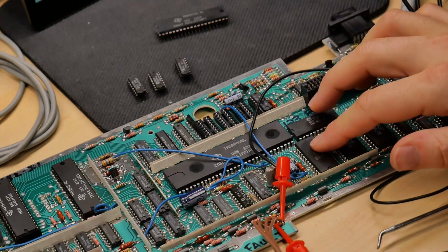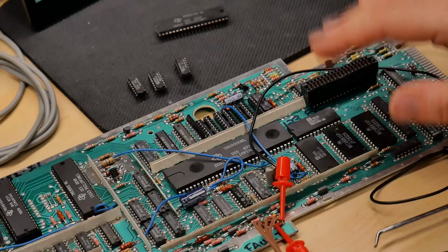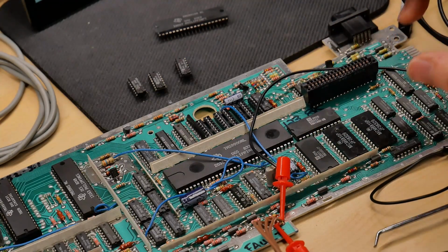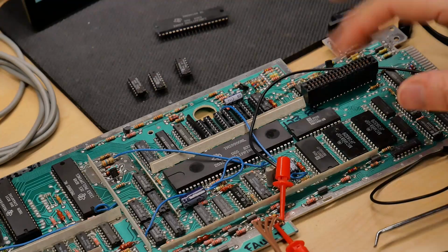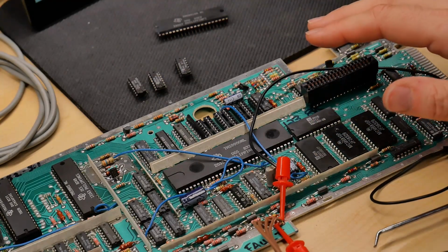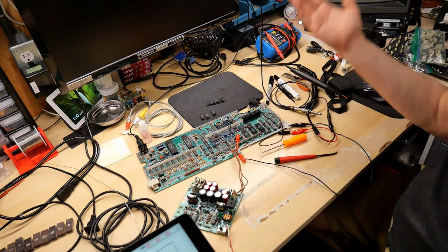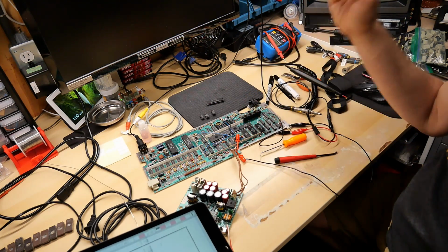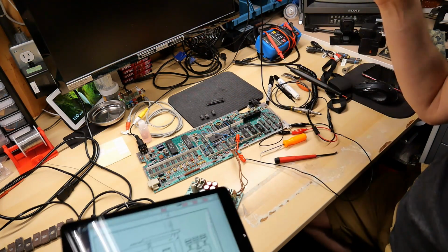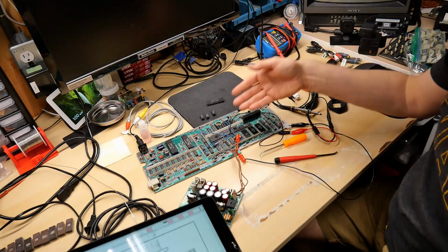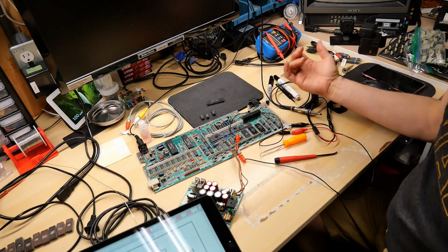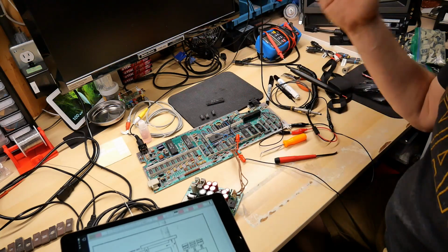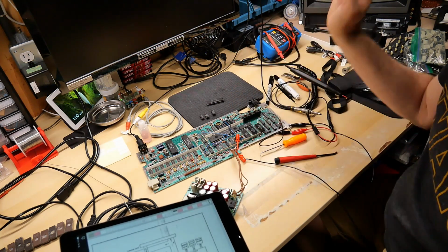I'm assuming these are maybe, hopefully, standard-ish ROM chips, although they might be the equivalent of a 2316. So I need to look at the pinout of these and see if I could replace these with EEPROMs. So I'm really struggling without the schematics. I need to try to find the schematics for this board so I could see if these ROM chips can be replaced with standard EEPROMs or if I'm going to be dead in the water. In fact, I don't even know if I have any of these SRAM chips either. So at this point, I'm probably stuck, but it's worth a try to see what these are and pull them out of this board.